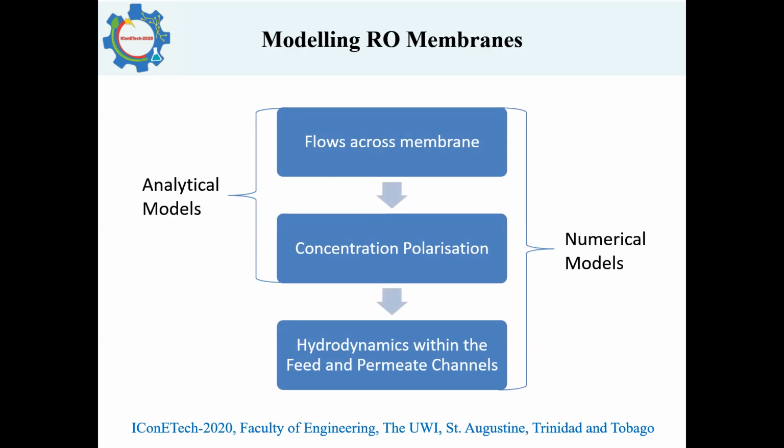With the advent of computers, we have now been able to make use of CFD-based analysis, and now we could actually start to take into account the hydrodynamics within the feed and permeate channels. But as I mentioned before, the problem with a lot of the models that we could find within the literature is that they make the simplifying assumption that membranes operate at constant rejection properties.